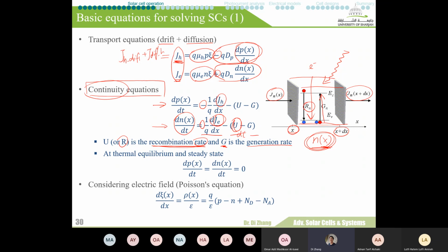And then from before, when we talked about the equilibrium condition and the steady state condition, if you wanted to use the continuity equation, it was actually singular back then, because obviously the number of electrons and holes are not going to change over time, unlike an excitation state. For steady state, we had dp over dt and dn over dt equal to 0. That is the previous scenario.